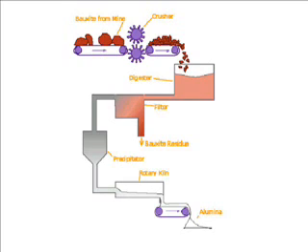The result is a liquor containing a solution of sodium aluminate and undissolved bauxite residues, which have iron, silicon, and titanium. These residues of iron, silicon, and titanium sink gradually to the bottom of the tank where the bauxite was washed and are removed as what is commonly referred to as red mud.